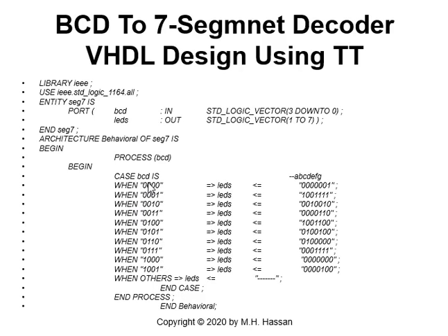The case here, BCD, within the process: when we have 0, 0, 0, it means when the inputs are 0, 0, 0, this will imply the LEDs will be assigned 0, 0, 0, 0, 0, 0, 1. As you see, this is A, B, C, D, E, F, G. Only G will be 1. And this is really the direct implementation of the truth table.